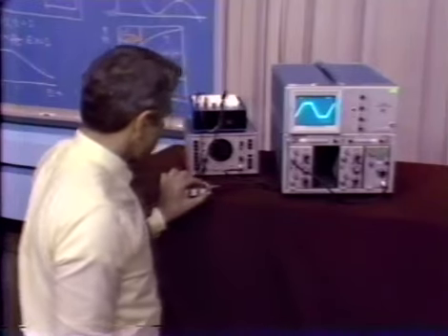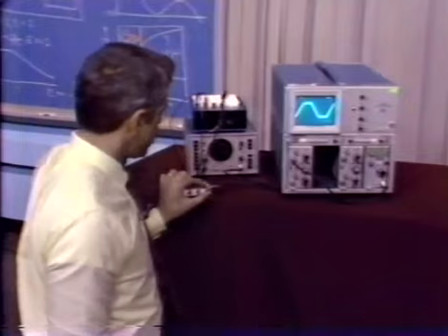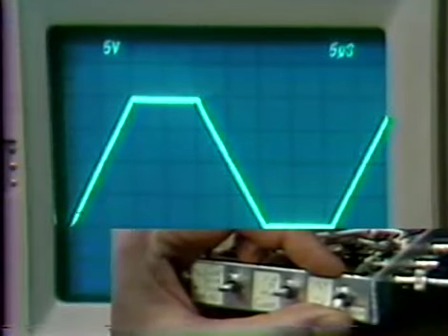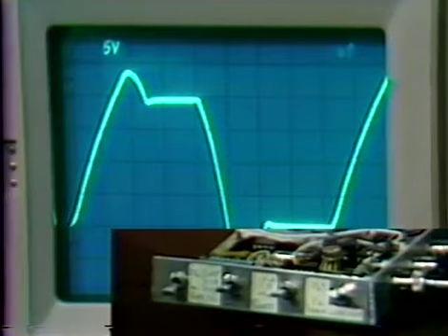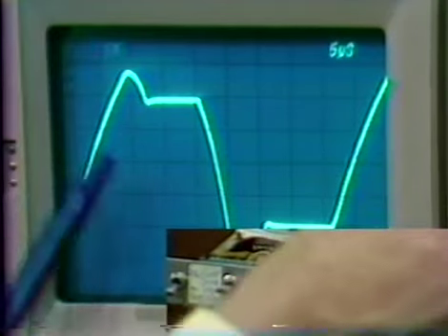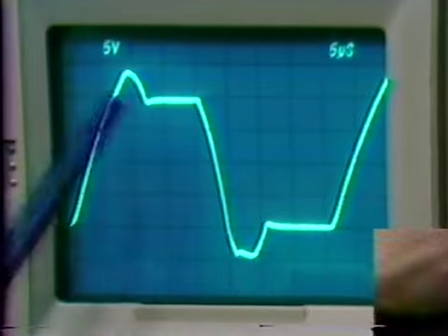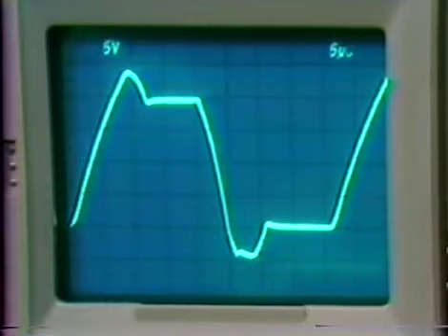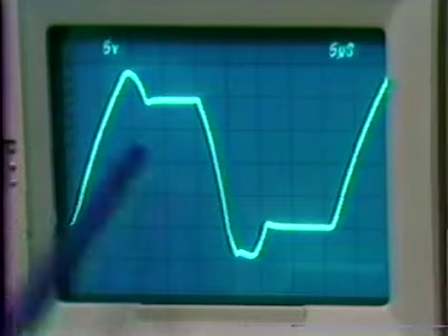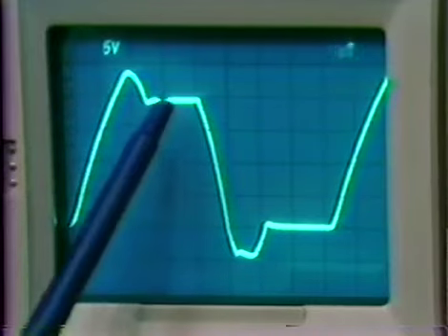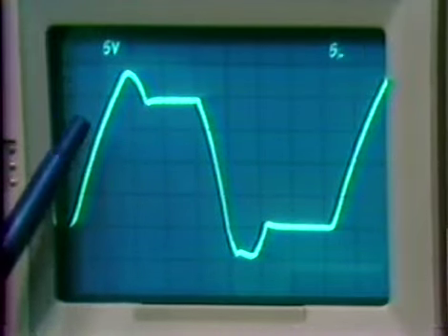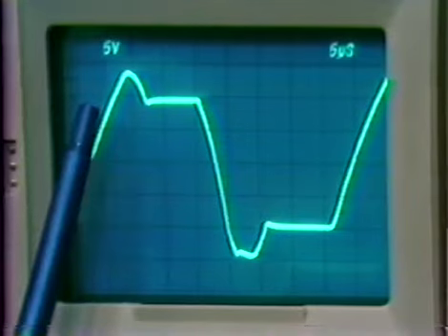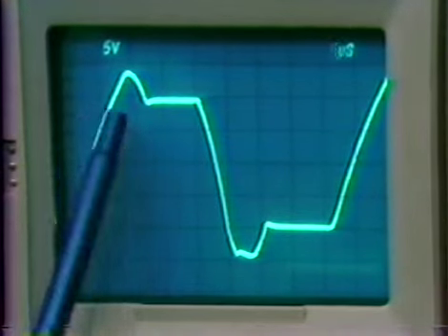Now let's look at what happens to the waveform if we use 1 over s squared compensation. We notice things get quite dramatically worse. Here again, we don't have quite straight line slewing or quite constant velocity slewing. Again, if you chase through the analysis, that's reasonable. These should be partially parabolic, and there's a little bit of that. But now what happens is here the amplifier should be entering its linear region, but it doesn't.